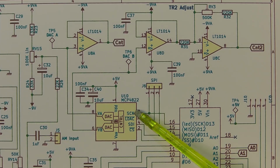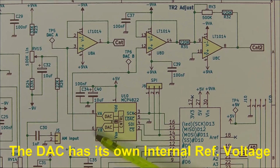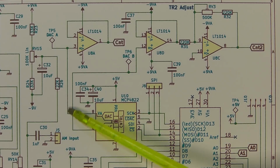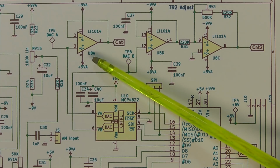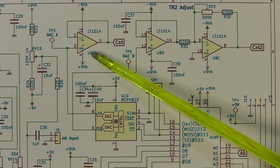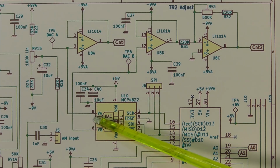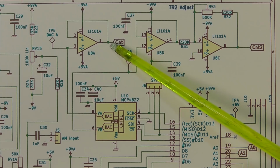It's the MCP4822, and it has two outputs there independent of each other. Initially we'll only be using output VOUTA, which is at pin 8, but at a later date we'll be using the other output on pin 6 for some future upgrades to this project. So pin 8, the output of the DAC, comes up here and it goes to an op-amp which is configured as a buffer. So we've got a buffer there which is just ensuring that we're not putting any loading onto the output of the DAC, and then the output of the buffer will then go into an inverting amplifier.